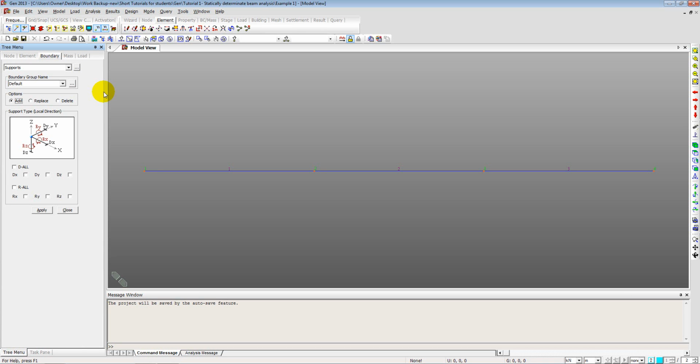So basically, for every finite element software, for a given node we have 6 degrees of freedom, 3 translation and 3 rotation. That is, displacement along the x, y and z axis, and rotation about the x, y and z axis, which you can see on the left side here. You have dx, dy, dz, which are the displacements along the different axes x, y, z. Rx, ry, rz are the rotations about x, y and z.